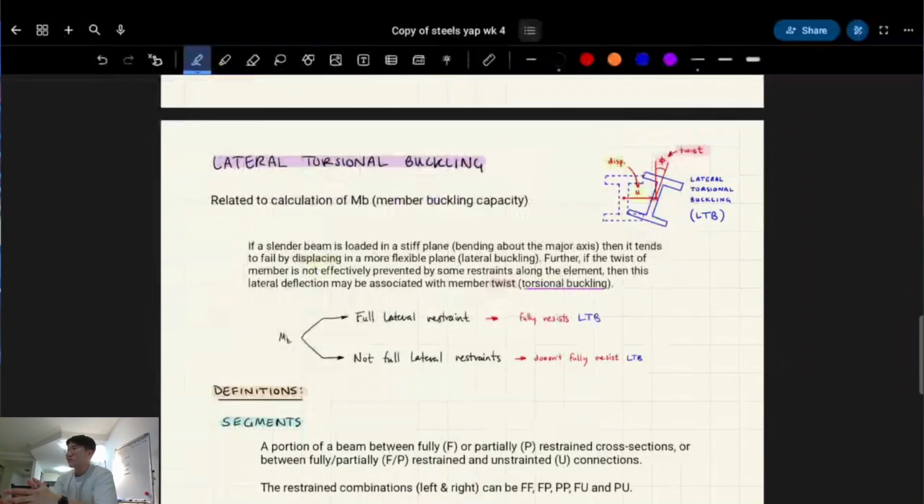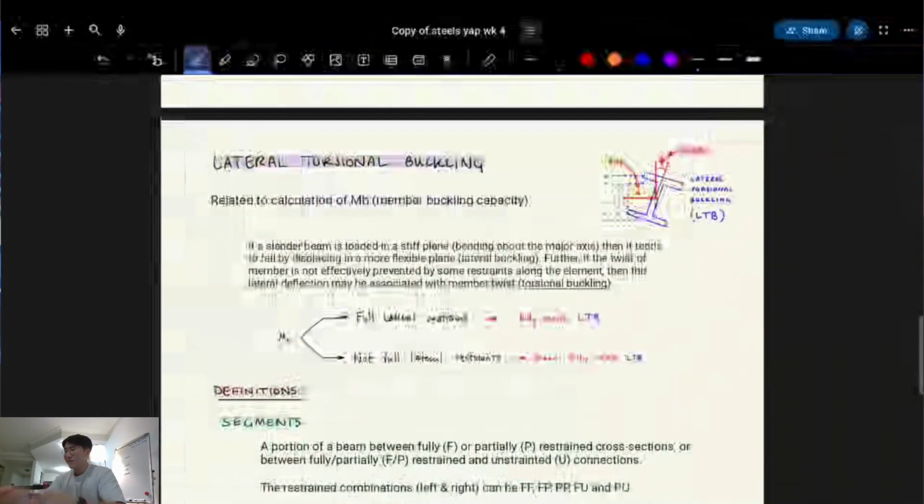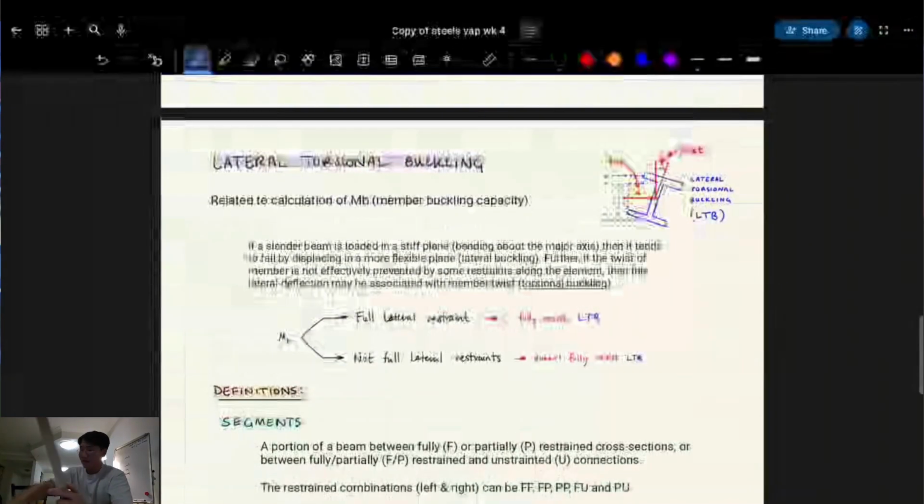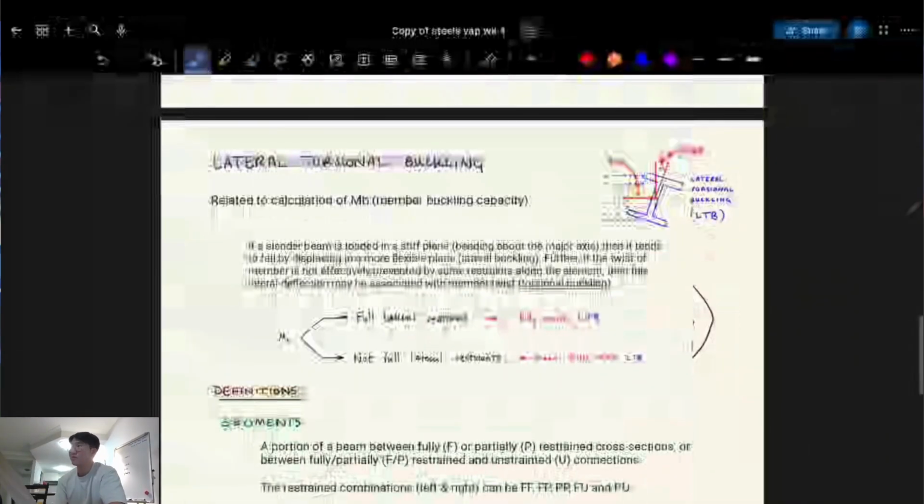I've explained lateral-torsional buckling conceptually, but do you remember how I said for compression that you can restrain it? If I'm pushing down on this in a compressive way and I restrain it in the minor axis, it does an S shape. So for anyone in the video, it does that if I restrain it in the middle, rather than fully buckling out. So this is for compression and Euler buckling, right?